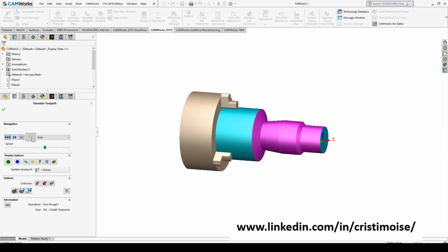First for me was the swarf machining, and then the enhancement for the curve features, and right now I was expecting this pinch turning for a long time, because I have a lot of requests regarding this option from my prospects. Also for turn toolpath, you have the collision check in y-axis. Maybe some of you will find this option useful. You will have these new options in the advanced tab of your turn operation. You have avoidance in y-axis.